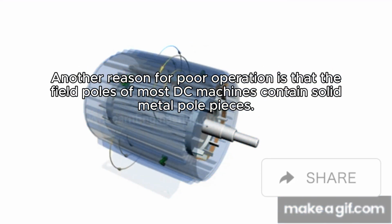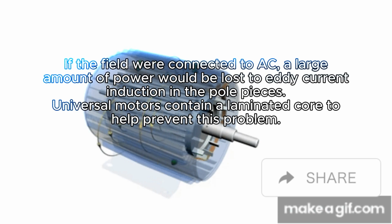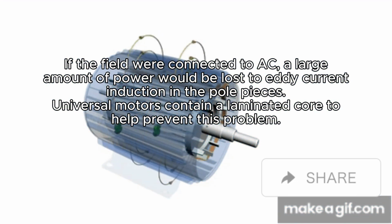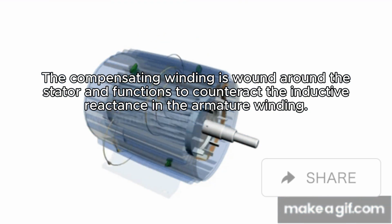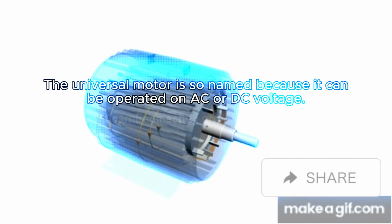Another reason for poor operation is that the field poles of most DC machines contain solid metal pole pieces. If the field were connected to AC, a large amount of power would be lost to eddy current induction in the pole pieces. Universal motors contain a laminated core to help prevent this problem. The compensating winding is wound around the stator and functions to counteract the inductive reactance in the armature winding. The universal motor is so named because it can be operated on AC or DC voltage.